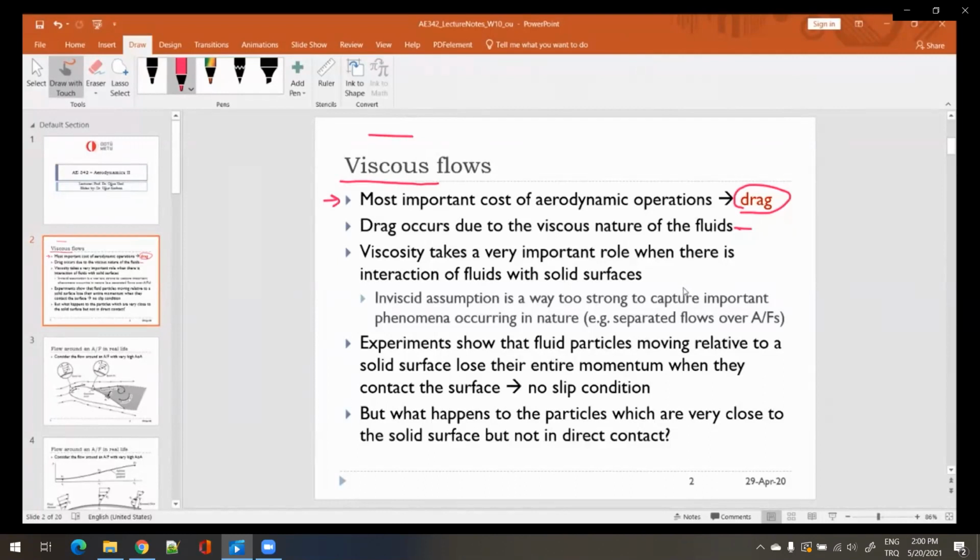It's very important for us aerospace engineers because drag is equal to thrust, first of all, in cruise flight conditions. A passenger aircraft spends most of its life under cruise condition, and under cruise, thrust is equal to drag. So engines have to supply just enough forward thrust force to balance the drag, so the forces are equal to each other. There will not be any acceleration, so it will be a constant speed cruise flight. Therefore, it's critical to estimate the drag correctly to size your engines.